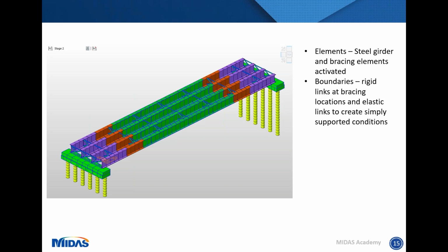And the other thing to note with the steel elements, which I'll briefly touch on later on for the composite beam, is that within the software it allows you to pick out the two components that make up your composite beam, so the concrete and the steel element. So for the composite element that you see here, all that's shown at the moment is the steelwork element, and the self weight is only taking into account the steelwork and not the added concrete.